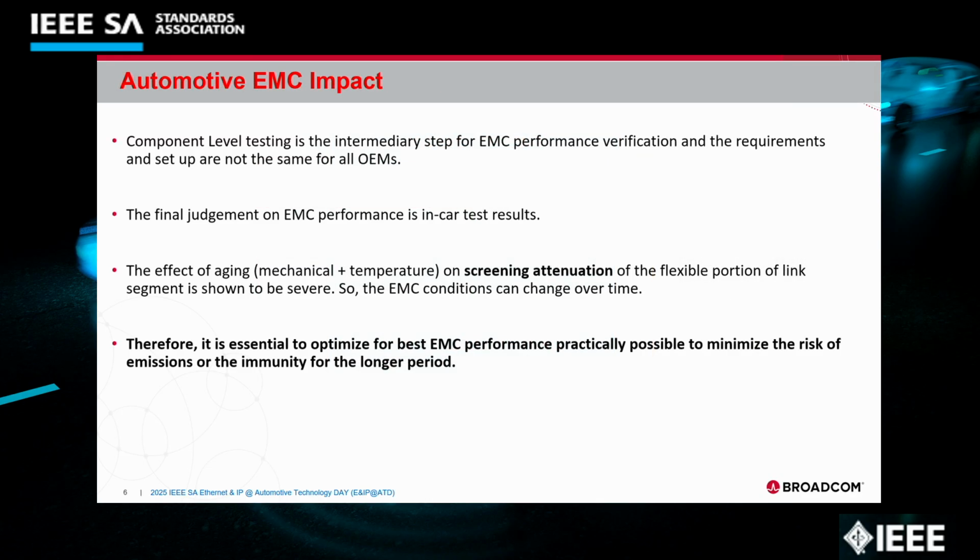Typically, silicon vendors concentrate on the IC level or component level testing, but these are the intermediary steps for EMC performance verification. They are the necessary conditions, but not the sufficient condition. The final judgment on EMC performance is typically the in-car test results. Recently, the effect of aging of the cable segment has been shown to be severe. So EMC conditions can change over time.